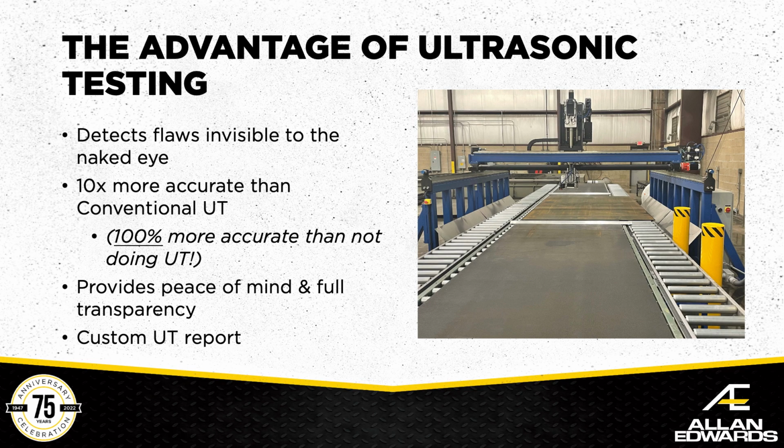So these reports are provided in our standard data package. So not only are you going to get the MTRs and you're going to get tensile test reports, post tensiles, post forming tensiles, but you're also going to get Charpies, and we're going to provide the UT report for every sleeve that we produce.